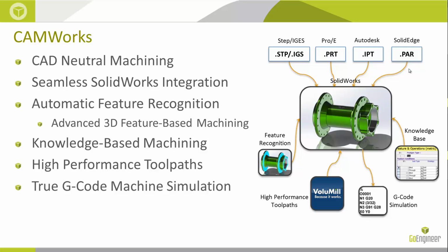But then at that point, we always translate what we see inside SolidWorks, or whatever CAM we're using, into a language that our machine tool can use. We call that G-code. And that translation is a step that can introduce some inaccuracies, right?